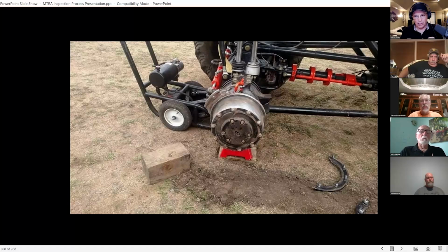The issue is that sometimes when you have crews that are not seasoned, they will not follow proper procedure in mounting the wheels. They get in a hurry, and they won't take the time to get the wheel perfectly centered before they tighten the lug nuts.